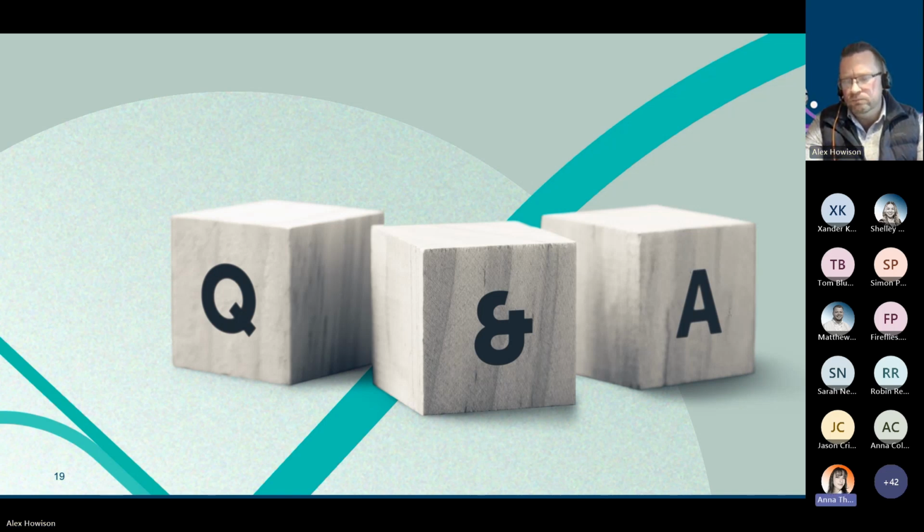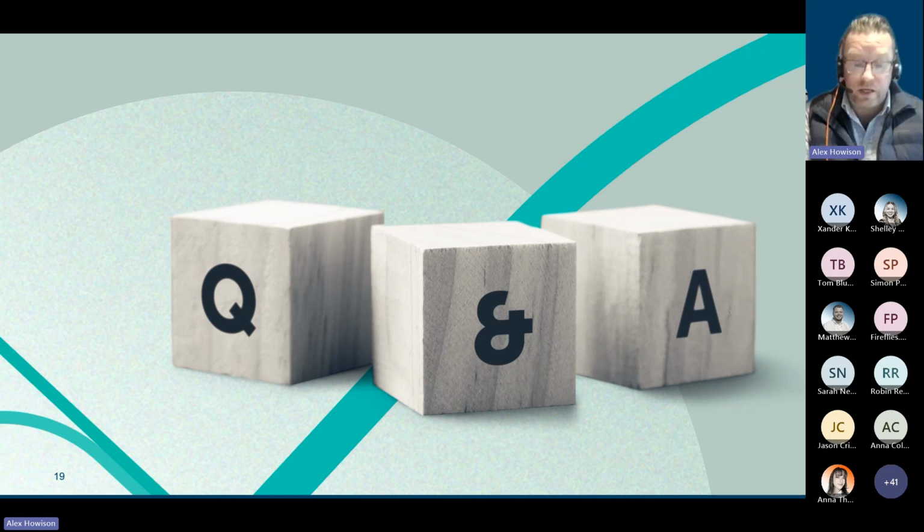Thanks, Alex. Next one is, will fault level headroom in the DNO network be an issue to bringing sites forward? I think fault level is a residual issue for any type of connection. We as a responsible private network operator do need to ensure that we've calculated fault level correctly for the assets within the private network, and we're having that conversation with the DNO or the TO that we're connecting to. So fault level will remain a bit of an issue, but within the private network, I think again we have that ability to look at fault level management.